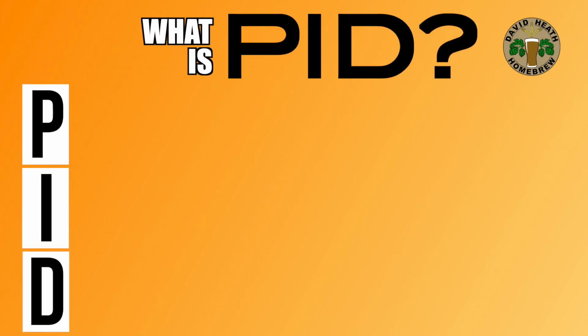A PID algorithm is actually pretty simple stuff when you break it down. It incorporates three values that can be tweaked to avoid overshooting and to aid in heating speed, which are the P, the I and the D. If these values are well set, then you will heat as quickly as possible and totally avoid overshooting. Not that a small amount of overshooting is really a bad thing, as it will not really have any real effect in the main scheme of things, so please do not beat yourself up over small amounts of overshoot.